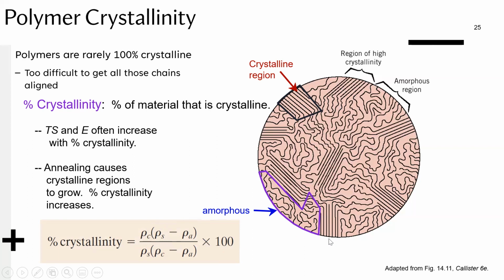Because if you make it more and more crystalline and organized, the density is going to go higher because you're going to get a much better packing. If you make it amorphous, the packing is a lot less compact as it's amorphous and random, and so the density is going to go down.